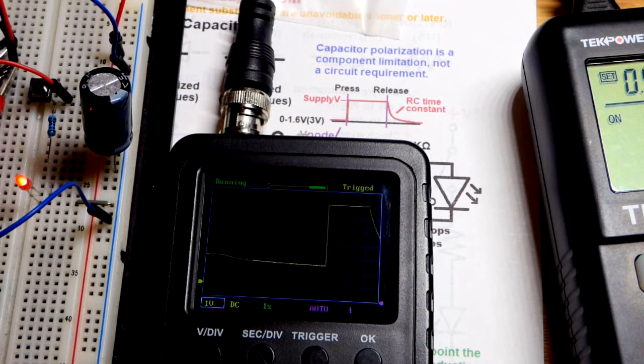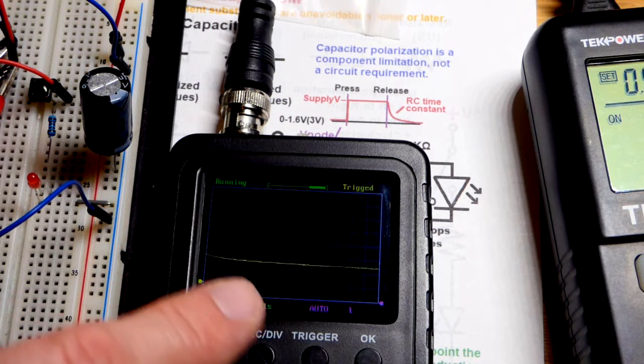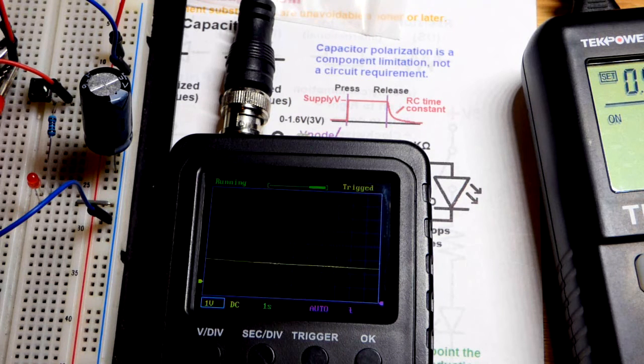You can see the LED's on, and now because it's a larger value capacitor going through 1 kilo ohms of resistance, it's dropping a little bit below that 2 volts. So the red LEDs block a little less voltage than green or blue ones. So you can see it is lower there now, and over time it may let a little trickle of current go through and discharge it a little bit more.